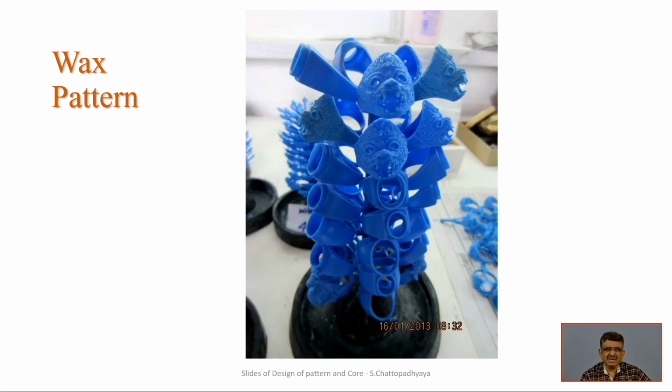So with 3D printing, the job becomes much easier in comparison to the age-old processes. So this is the tree associated with those wax patterns, and it will be done in one go, many products will be manufactured, and those things will be done with the subsequent steps. We have discussed all those different pattern materials and their utility in terms of application and geometries, and last but not the least, we have seen the wax pattern, which is responsible for producing intricate surfaces related to the manufacturing of ornaments, aesthetic things, and intricate shapes, another part for typical application.